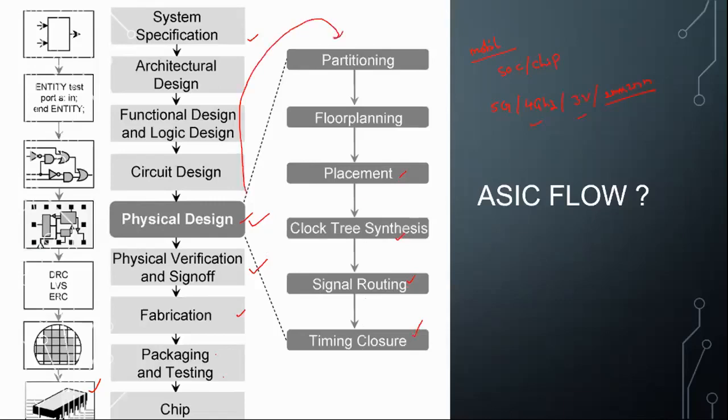Once my timing and DRC are clean, I go to physical verification, which is majorly concentrated on DRC, and the sign off. Sign off means IR sign off. We have different sign offs, IR, formality, and everything should pass. Then only we go to the fabrication. If anything goes wrong, we can come back.